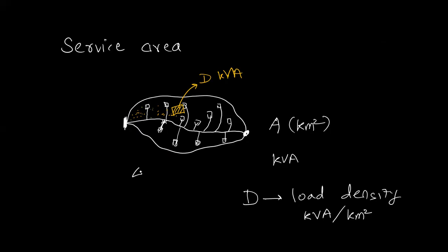So we are interested in the maximum voltage drop that appears along the length of the feeder. And the system operator bothers about the total power loss happening inside the system. So these are basically two quantities that matter while planning a new substation or feeder.